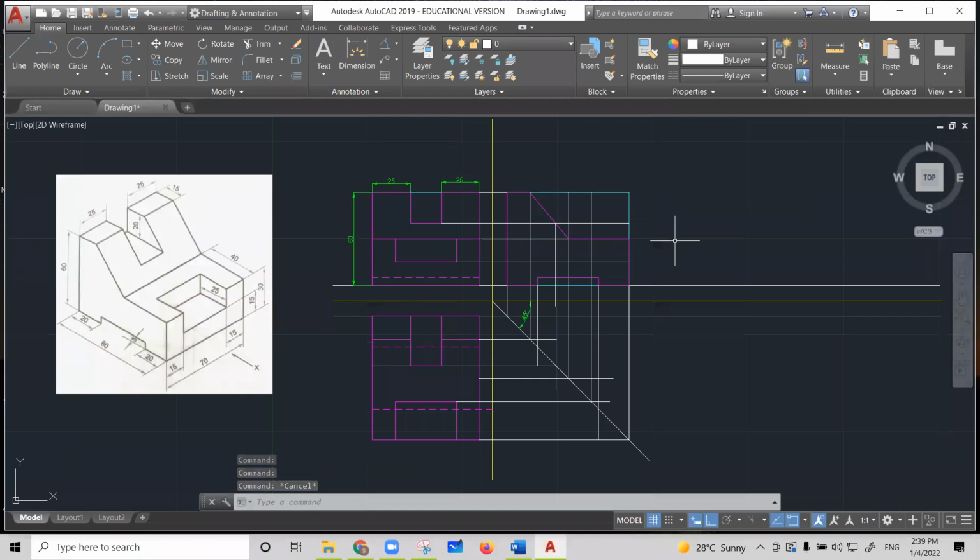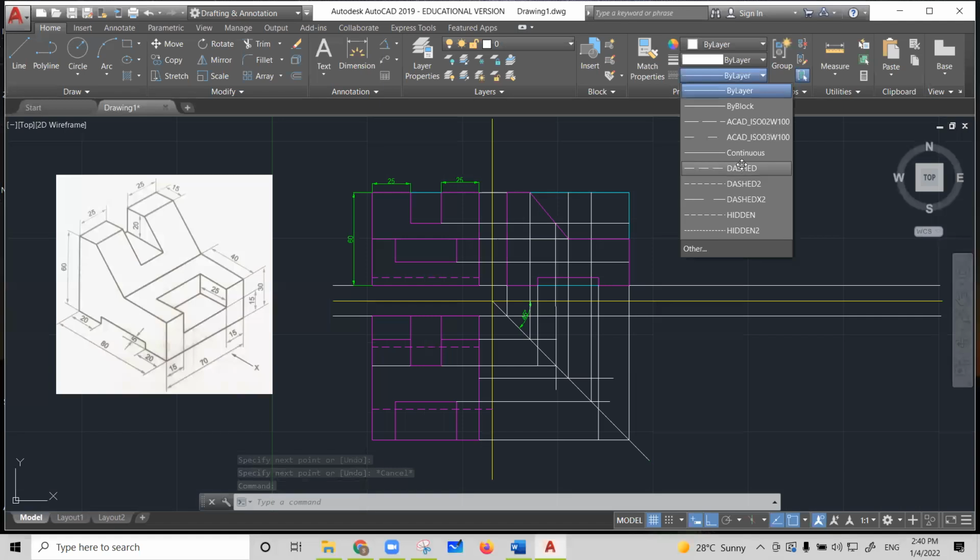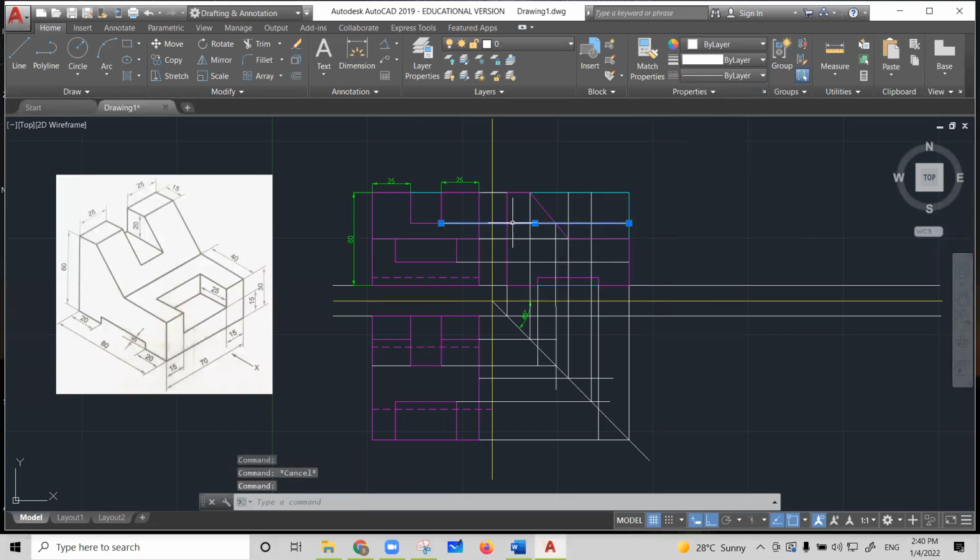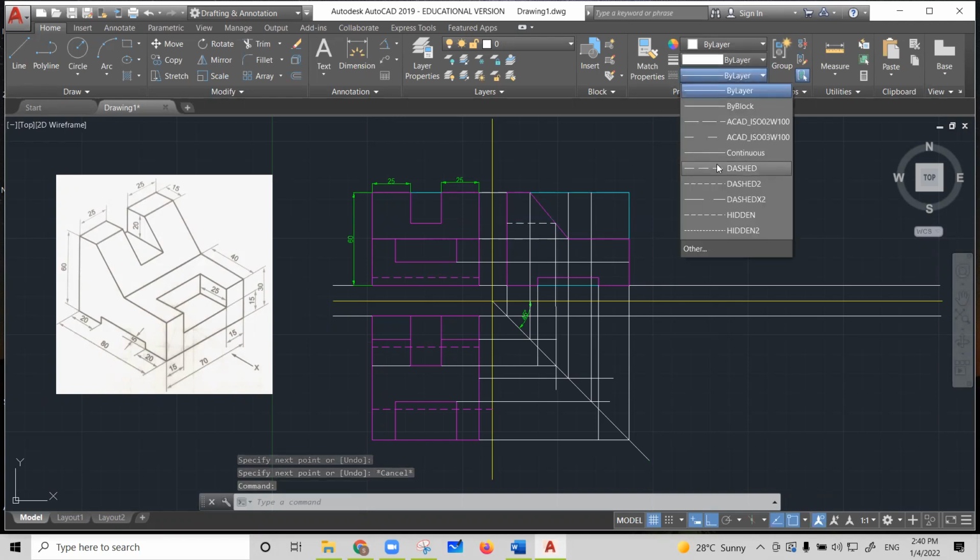Okay, and now as far as your top view and side view are concerned, only one thing is not visible, that is nothing but this line. Okay, this slot is not visible to you. So first of all, you just remove this line. Okay, and you find this slot in this dotted line is visible to you, not up to this. I have to take this point up to this length. Okay, so now I convert it into the dotted one.